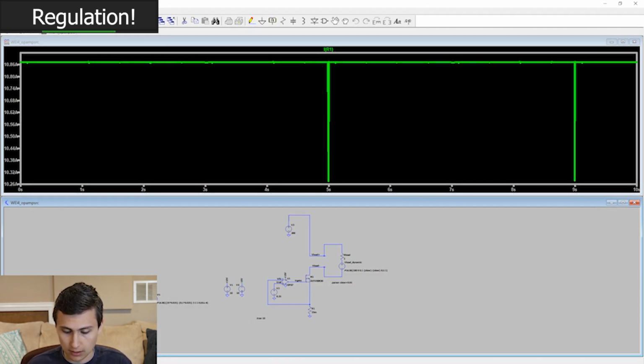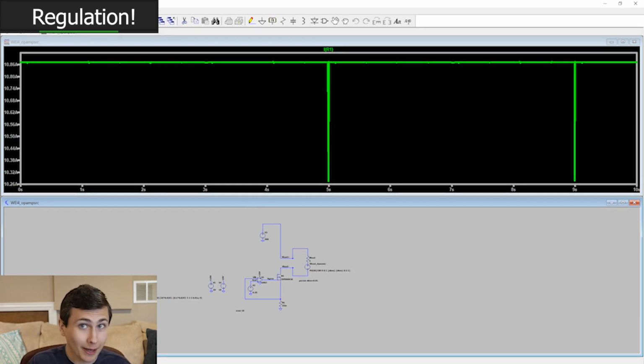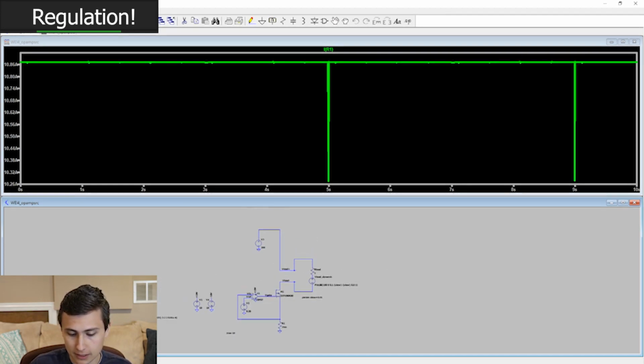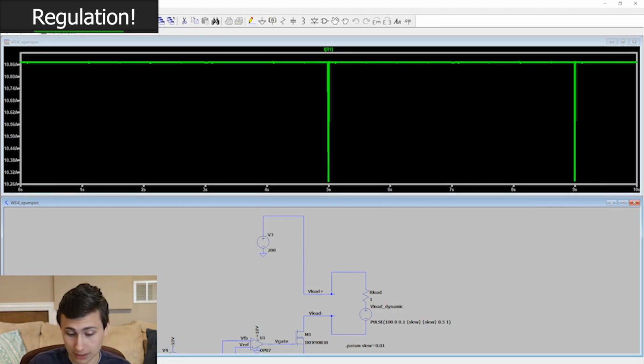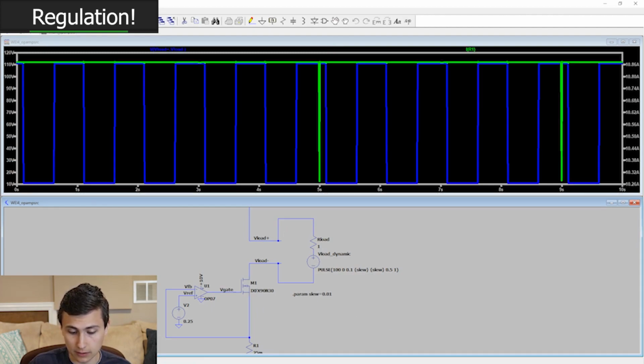That's 8% error, within 10%. It's not half bad. I think we can do a lot better with a very similar circuit, but as a starting point, compared to what our BJT was accomplishing, that is not half bad. Especially because, if you remember last week, the load, the operating point, the bias point, really affected the current regulation.